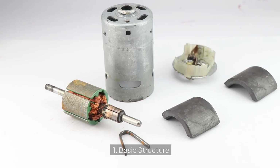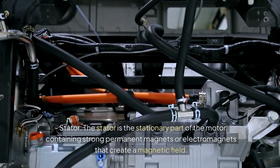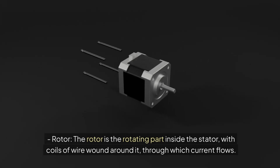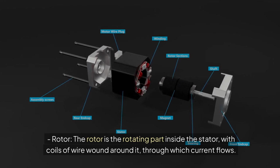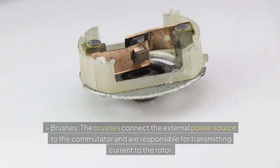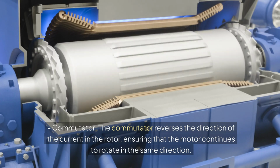1. Basic structure. A DC motor primarily consists of the stator, rotor, brushes, and commutator. Stator. The stator is the stationary part of the motor, containing strong permanent magnets or electromagnets that create a magnetic field. Rotor. The rotor is the rotating part inside the stator, with coils of wire wound around it, through which current flows. Brushes. The brushes connect the external power source to the commutator and are responsible for transmitting current to the rotor. Commutator. The commutator reverses the direction of the current in the rotor, ensuring that the motor continues to rotate in the same direction.